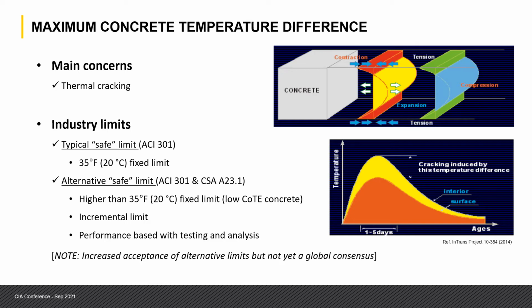that are mainly related to the mass gradient occurring between the maximum temperature and the equilibrium temperature. That's a very common term that is used for traditional mass concrete. But the temperature difference limit associated with standards in the United States and Canada is related to the temperature difference between the core and the surface. So that's what we're going to be talking about today.